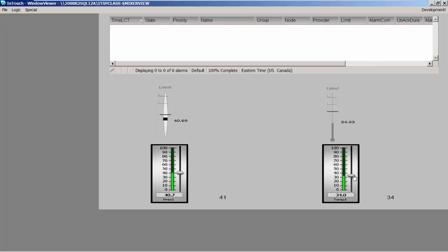Same thing here on this other temperature variable I have over here. You can see I have this set for a different priority. This is a priority 4 alarm. When I get this temperature alarm, high on this temperature alarm gives me a priority 4, different color scheme. And if I give this a high, which is a level 3 alarm or severity 3 alarm, it gives me that condition.